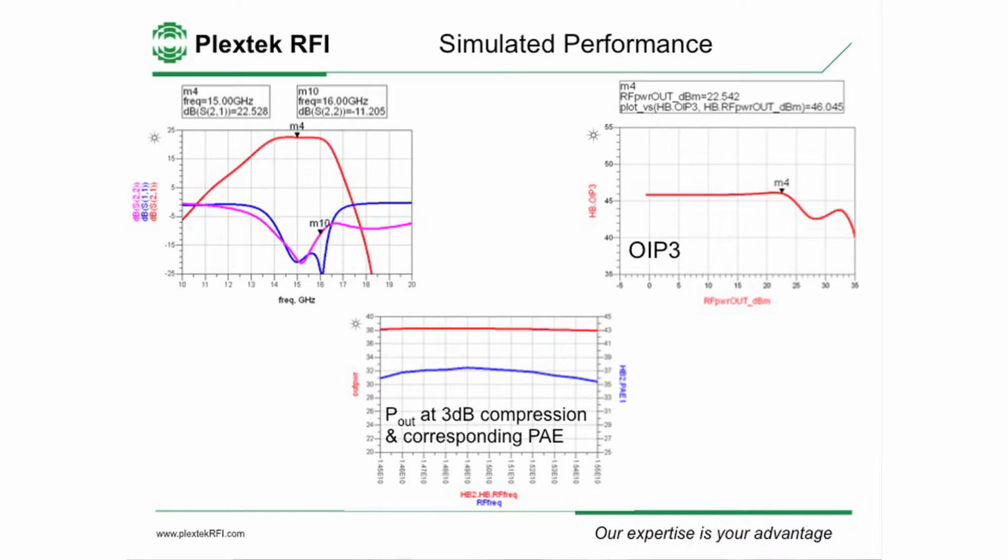You have to be very careful when you're looking at commercially available GaN ICs. This is my top tip for you. They have this metric PSAT. Watch out for how far into compression you need to drive that IC to get to the PSAT point. Some of them are fine, but I've seen 10 dB. And this is our PAE here, around about the 37% mark for the two-stage IC. This is our output IP3 here, and we're achieving 46 dBm at the 22 dB per tone level.